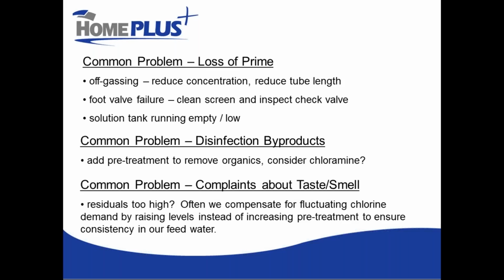So the last few common problems that I'll hit on is loss of prime. This happens when the pump is unable to pump because air has got into the system. That can happen if the solution tank runs empty and we start sucking air into the system.